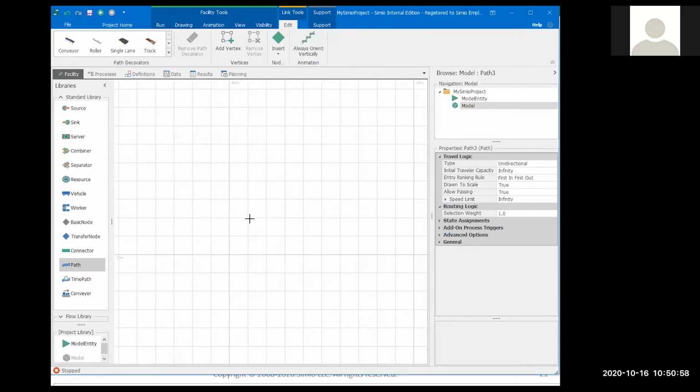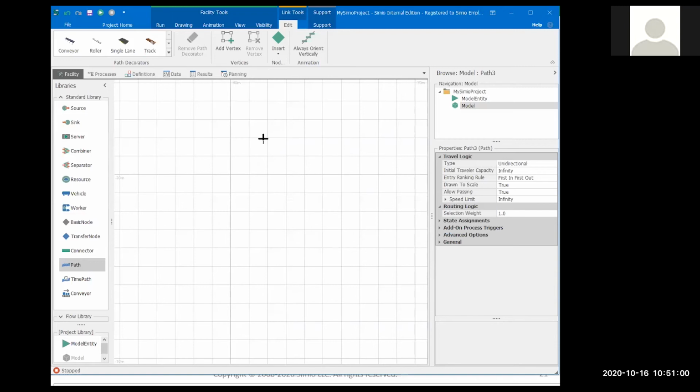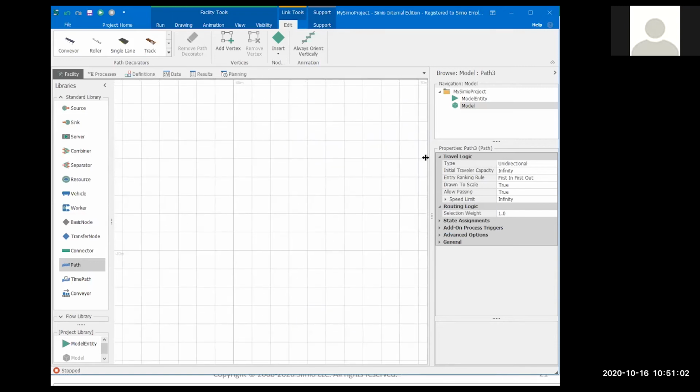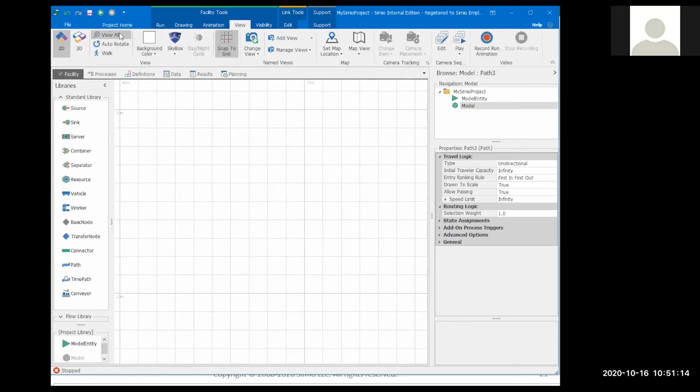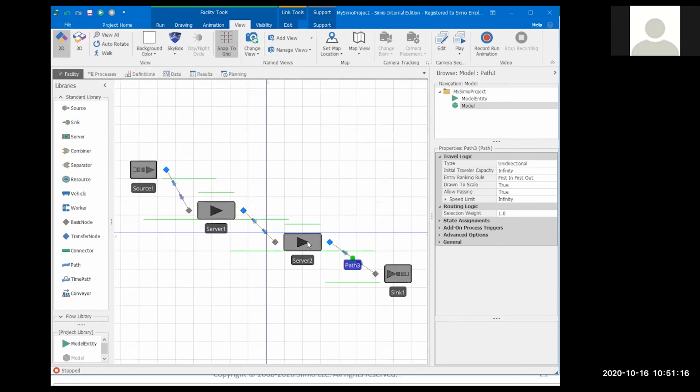So whatever direction I'm going off screen in, it's scrolling me automatically in that direction, and you can often get kind of lost. When that happens, you can hit escape or right click, then go up to the view ribbon and say view all, and it brings you back to your home screen. So get out of multi-place mode and then go to the view ribbon to get back.